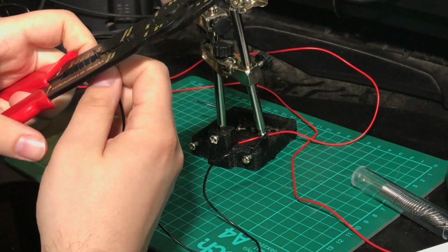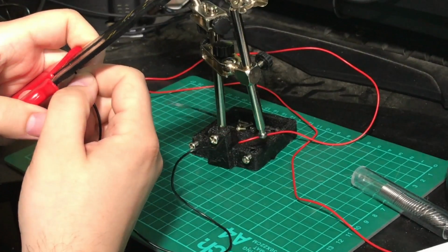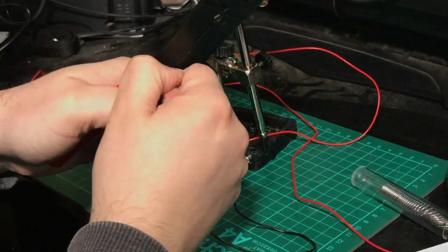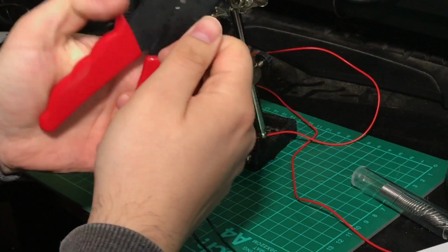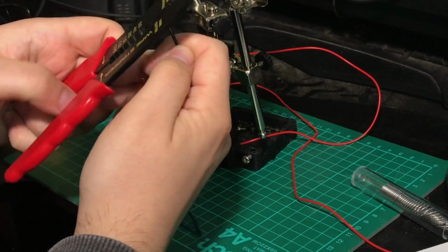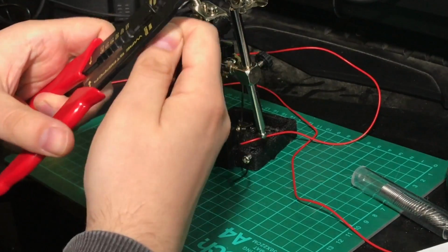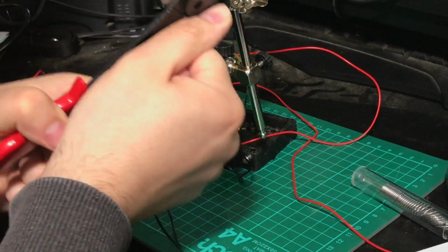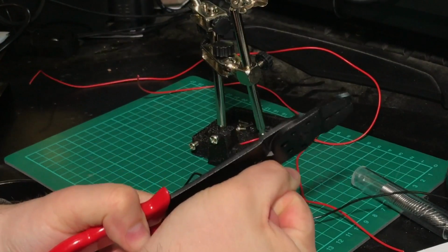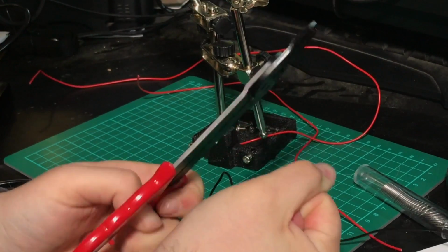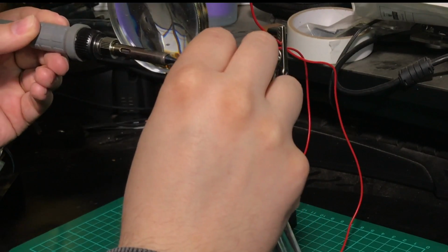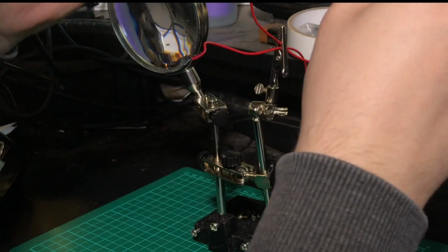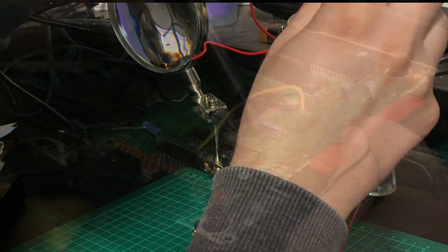Next, take 3 lengths of wire. The colour is your preference. It's easier if they're all different colours, but I only had red and black, so I'm using 2 red wires to solder to the on positions of my switch and a black wire to solder to my switch's off position. It helps if they're a little longer than you need, so you've got a little room for error. Strip a little bit off the end, give the exposed end a little twist and tin it by applying a small amount of solder so that it's nice and shiny. Do that for all 3 wires.